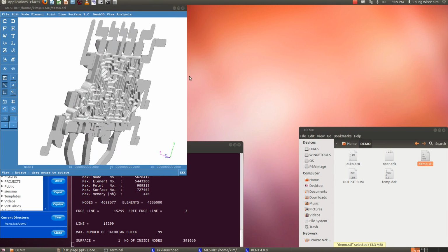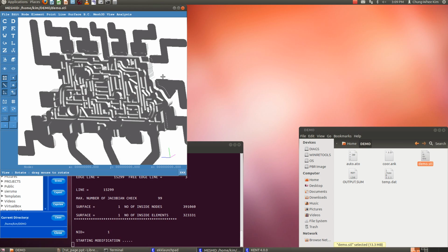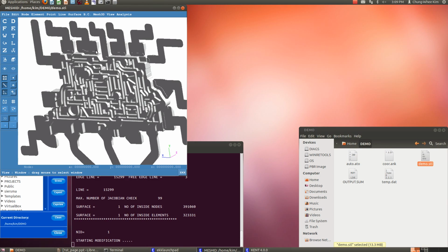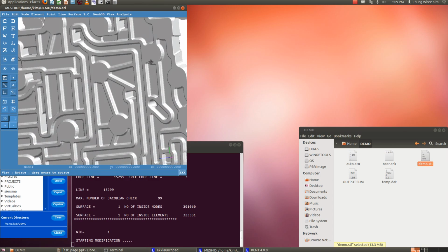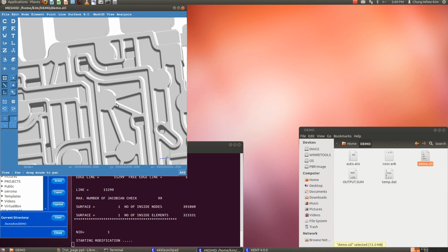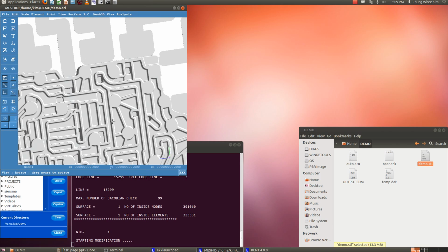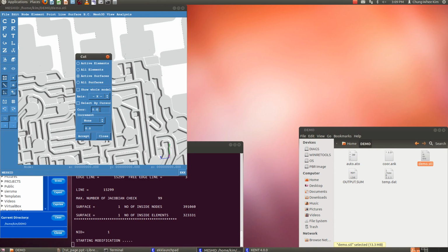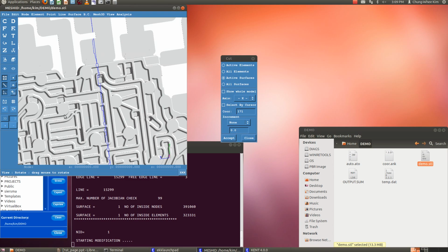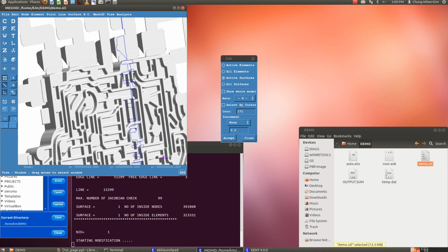Clearly you can see all sorts of channels and contours in this complicated casting geometry. If you zoom in, you see a little bit better how those channels are defined. Lots of smooth curves, lots of radii. I can go in and take cut sections. I'm going to take a cut section at 171, and that's going to go right through an overflow so that I can compare the thickness of the gate to the overflow to the thickness of the casting.